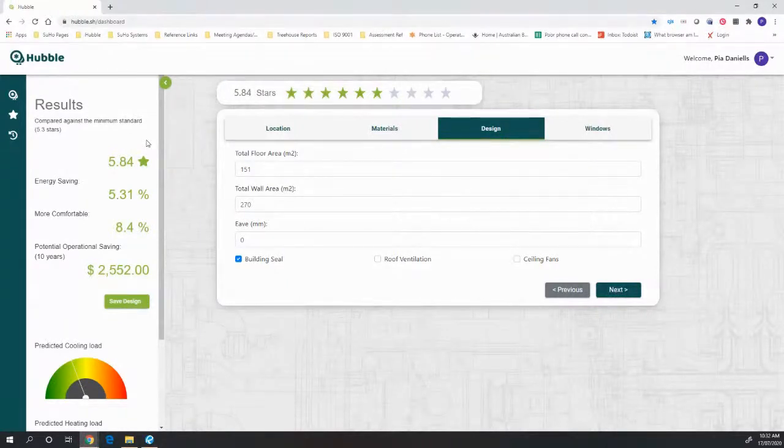So when designing a building, we want to consider things like what is the purpose of the window? Is it letting in natural light? So proportionally, how big does it need to be to achieve that outcome? And what is being seen through that window? I mean, if you've got a really large, floor to ceiling window looking at a neighbouring fence, are you really getting value out of that window for essentially putting a hole in the wall? So those are some of the things that we need to consider when we're designing a house.